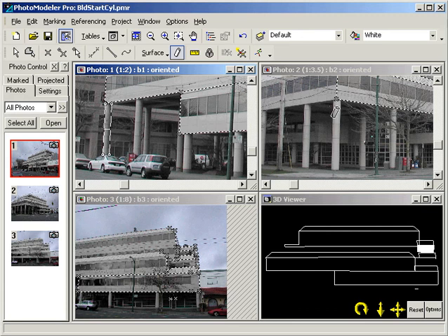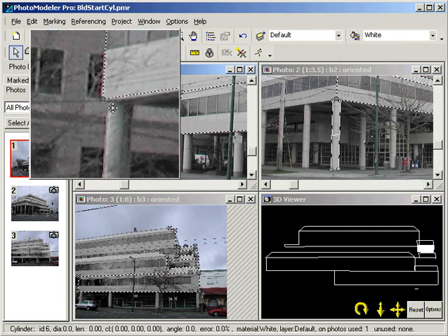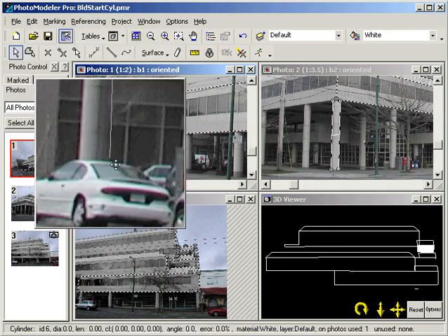We repeat the steps and mark the cylinder in photo 2. Again, the endpoints do not need to match, but the cylinder edges should be marked along the same position. We use the Alt-Zoom feature to adjust the cylinder positions. If you have difficulty seeing the edges in the photograph, Image Enhance can be used to adjust contrast, brightness, and gamma so the features are more visible.